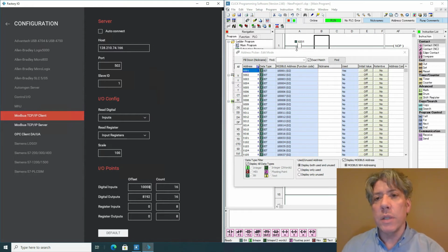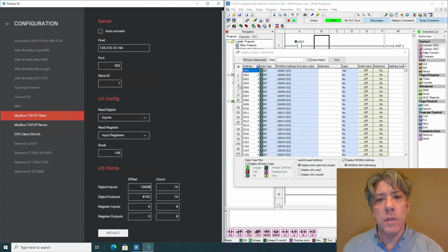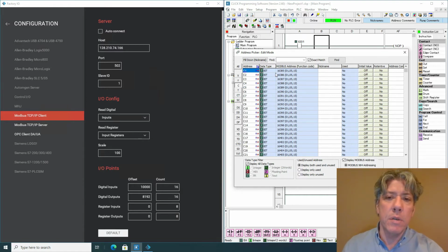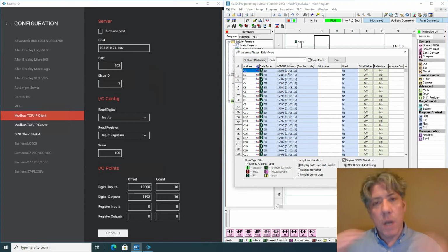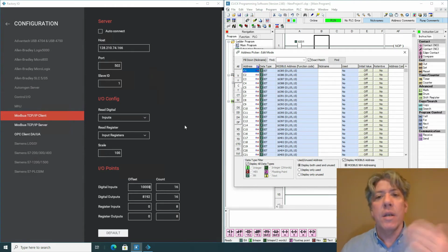So what I'm going to do instead is connect the button up, instead of literally to the computer or to the PLC, which I can't do because the button's not a physical button. I'm going to connect it up to a memory address instead. So we're going to hook it up to a control relay. And you'll notice that the Modbus address for the control relay starts at 16,385. Now here's something kind of strange. There's an offset of 1 between these two. So if you read 16,385 as the address here, the address you need to give Factory I/O is 1 less than that. So it's 16,384.